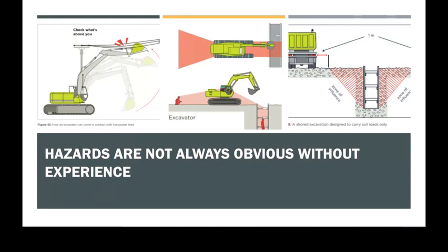So if you're piling up soil you've excavated, it actually needs to be the depth of the trench away from the trench plus a metre. So if you're 2 meters deep, you're 3 meters away is where you're putting all your soil. It's quite a long way away, further than you'd think. But if you pile it up close to the trench, there's a whole heap of extra load, which is likely to cause it to collapse.